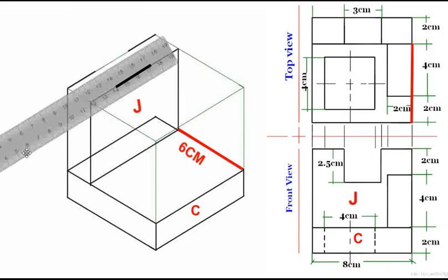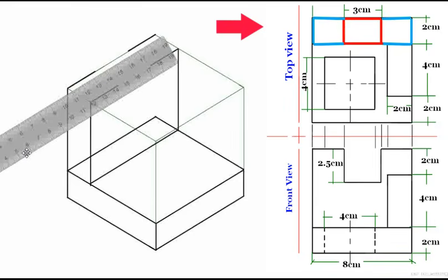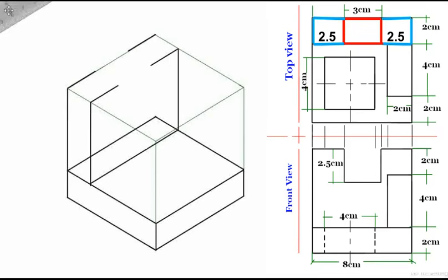From the top view, lines parallel to the Y-axis appear as points, while lines parallel to the X-axis appear wider. We can see a partition from the top view. To create it, measure 0.5 centimeters from the starting point, then 3 centimeters from that, and the remaining is 2.5 centimeters. Then, connect the endpoints of the extruded lines.